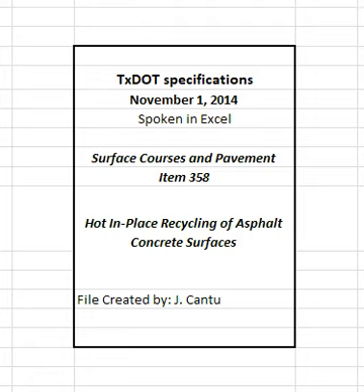4.8 Traffic. Allow the compacted pavement to cool to 160 degrees Fahrenheit or lower before opening to traffic unless otherwise directed. Maintain the surface of the recycled pavement in a condition suitable for the safe movement of traffic. Power broom the pavement surface to remove all loose particles if needed.